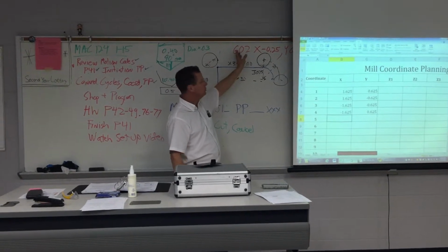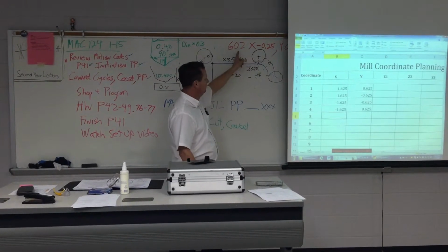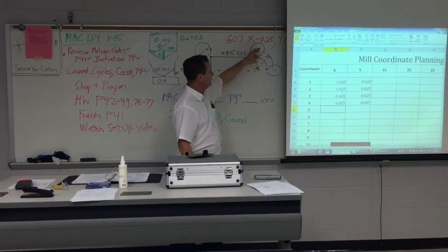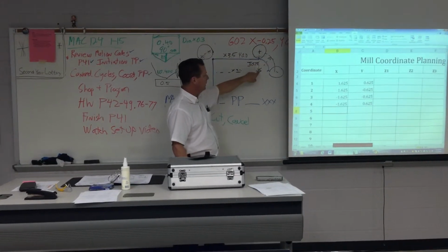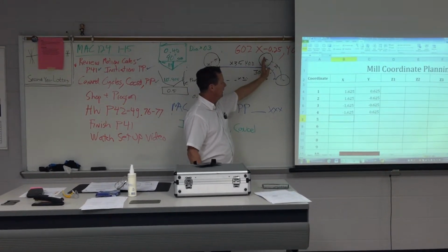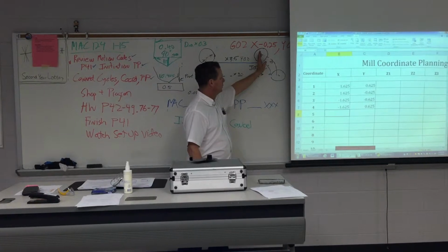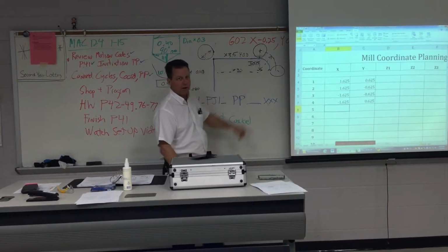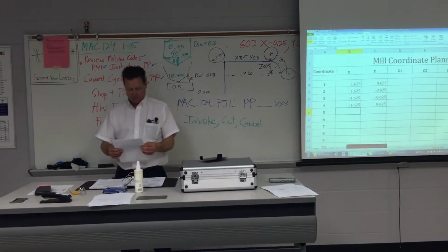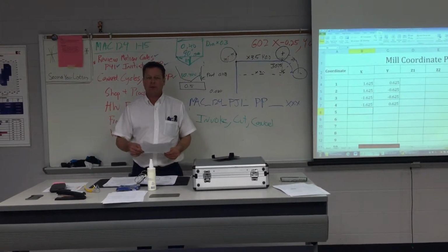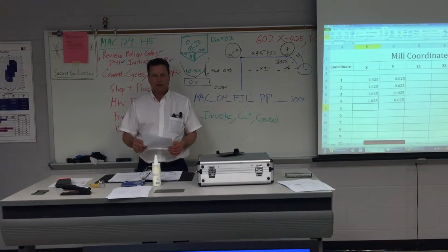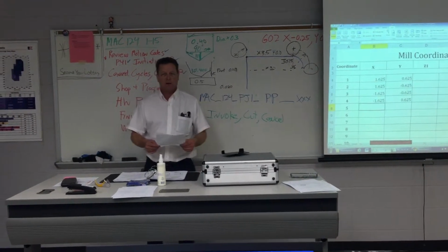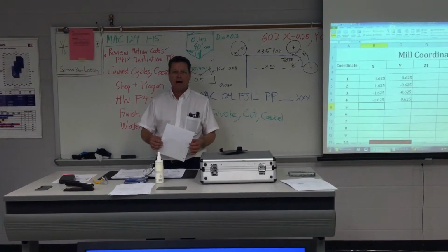On all motion codes we have the end point, and then we tell the vector to where the arc is drawn from, and so the tool will go from here to here, tied back to the vector where the arc center line is. So go over that 3 or 4 more times till you understand it, because all of our radiuses are going to be programmed on the mill with I and J.